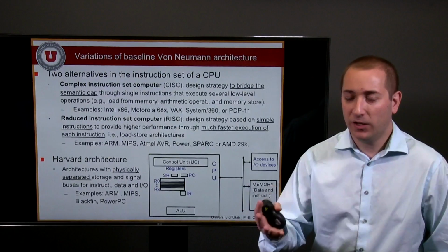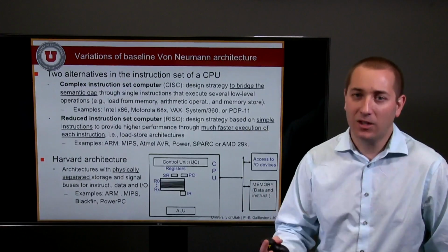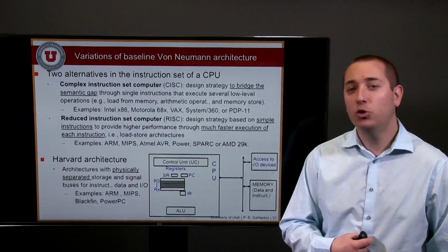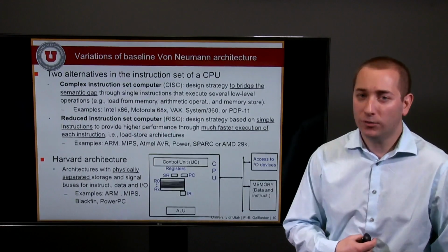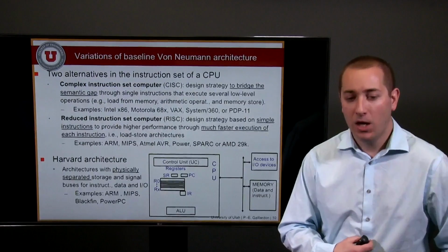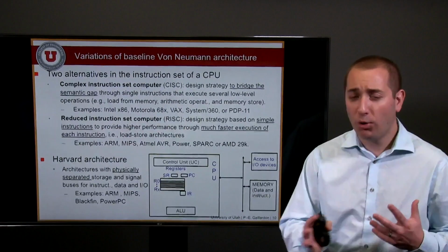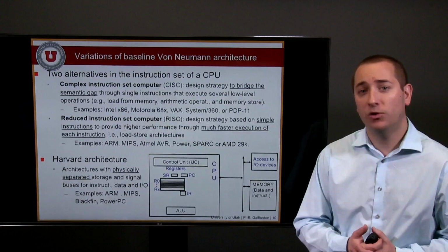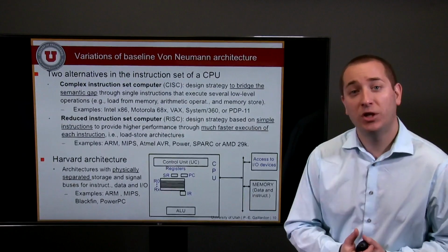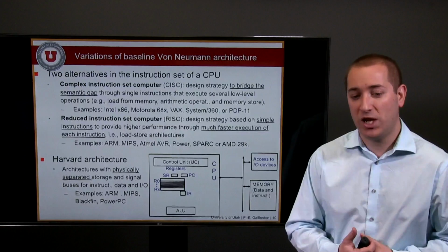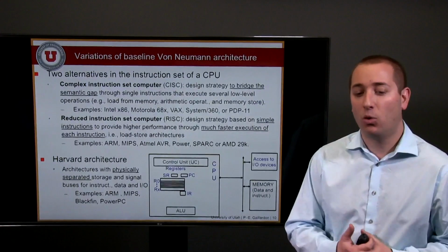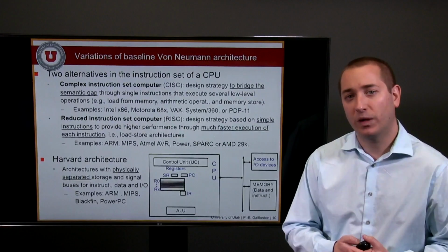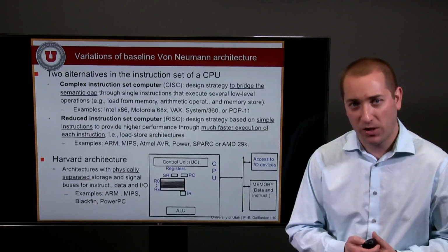Another alternative is to use the Harvard architecture. Instead of the basic von Neumann model, which has a memory that contains both program and data information, the Harvard architecture will have two separate memory buses, one for the instructions and one for data. That will provide you better bandwidth, and it's a very commonly used architecture in digital signal processors, DSPs, such as Blackfins or some advanced ARM, where you do have this kind of arithmetic operation that is hard.